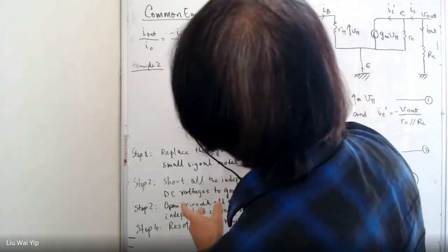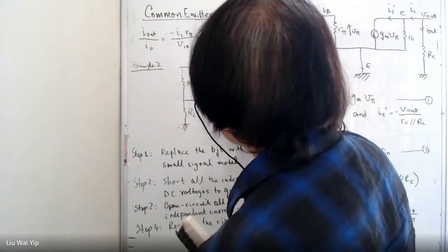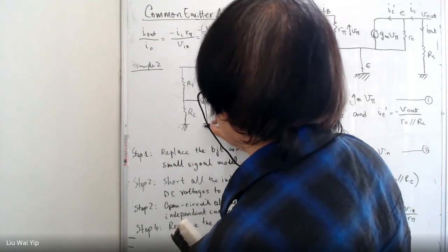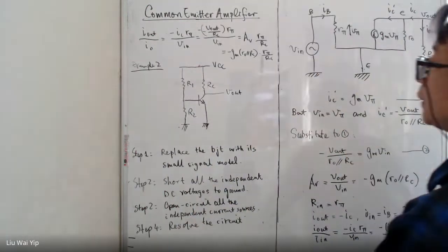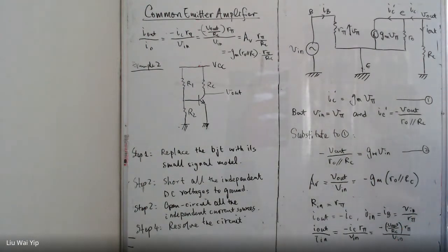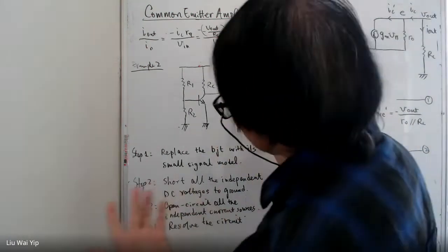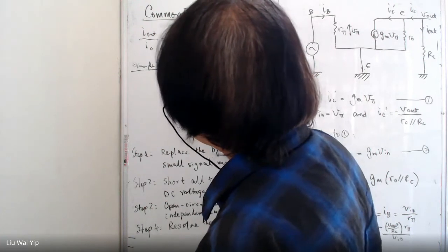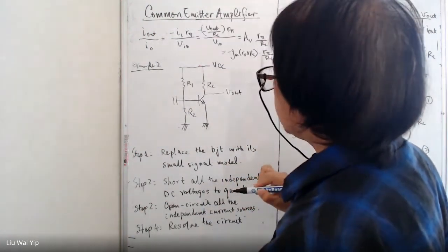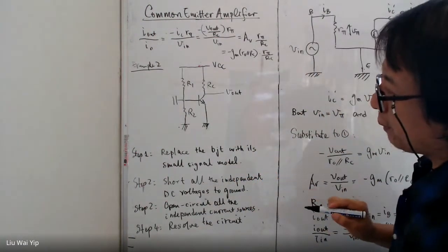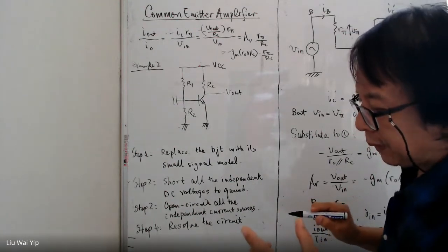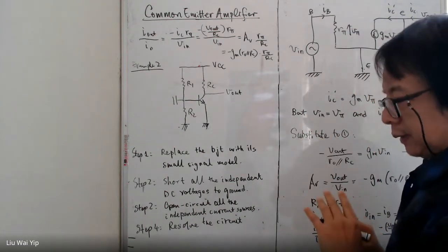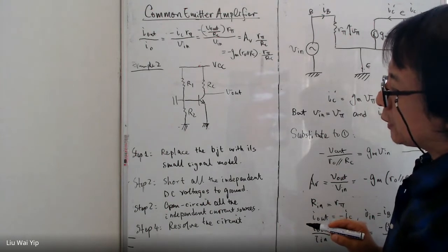So this is basically the bias level. And now how the input and output can be applied to the circuits. It's very easy, and what we need is just a coupling capacitor. And this coupling capacitor can filter off all the DC voltage.